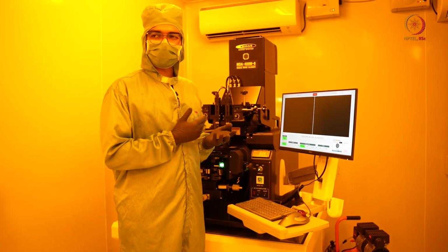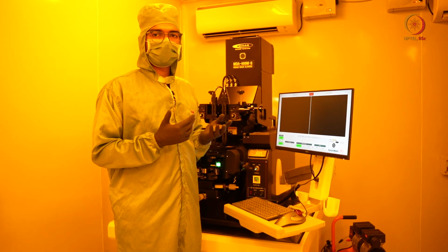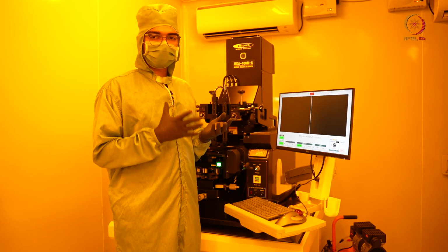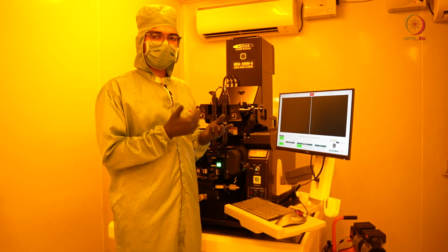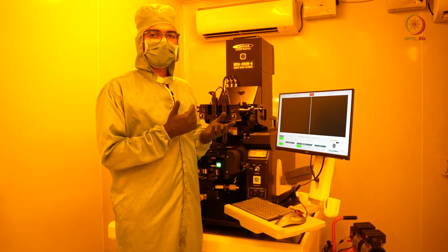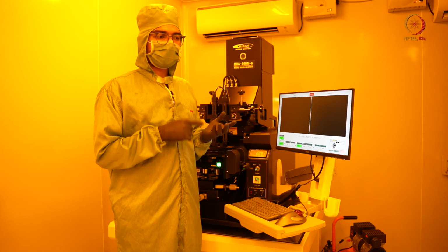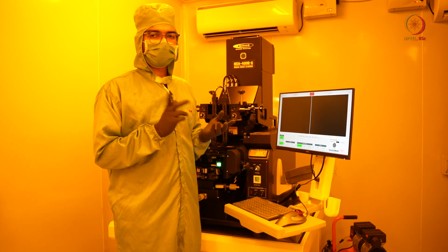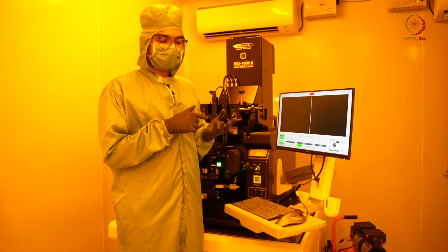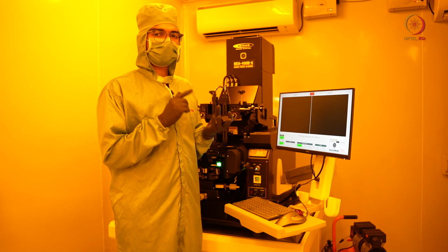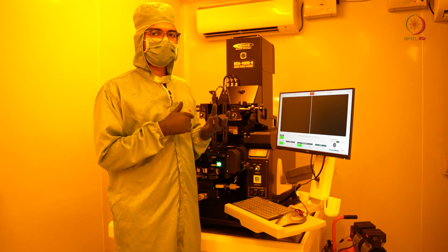Now the next step after lithography, or the exposure, for a positive photoresist like the one we use is something known as hard bake. Sorry, soft bake. So we did pre-bake already, then we did exposure, and now we are going for soft bake. After soft bake, which happens at 110 degrees Celsius for 1 minute or 60 seconds, we will go for the development process. In the development process, the exposed photoresist, since this is a positive photoresist, becomes soft, right? So the exposed area will get removed. Now we will see that.